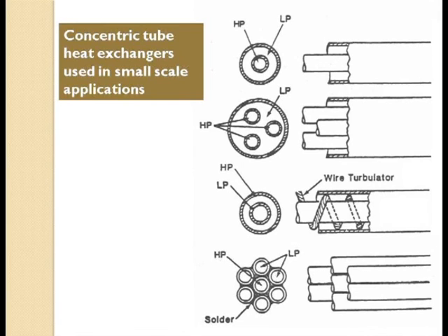Across the solid oval, heat will be transferred from this fluid to this fluid, and this is a standard practice in heat exchanger, tube in tube heat exchanger. Now you can also have multi tubes placed inside another tube. So you can accommodate 4 types of fluids: 1 fluid, 2 fluid, 3 fluid, and another fluid is in between the tubes, the inner tubes and the outer tube.